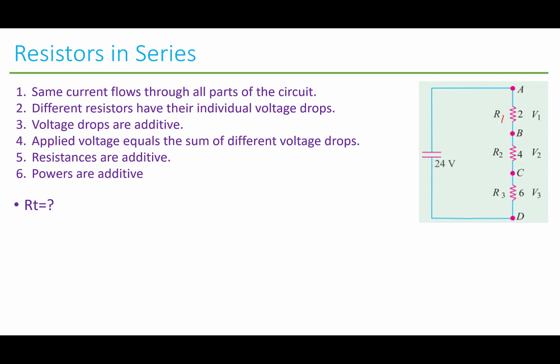So a series connection is basically, this is a resistor, right? So R1, it has two terminals, terminal 1, terminal 2, and we have another resistor, say terminal 3, terminal 4, R2. Now two elements are connected in series whenever they are kind of in a handshaking mode. That means if we connect these two, then these two are connected in series. Now if we have another resistor right here, two resistors are said to be connected in series whenever they have only one common node, this one.